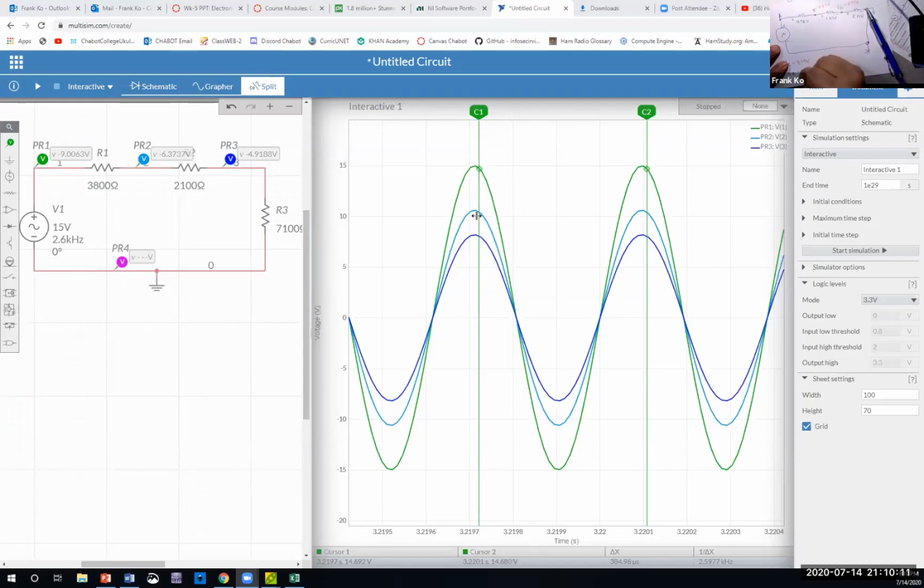10.62 volts, so that's 10.62 volts. And then the voltage at point A means my red probe goes way over here. Well, what is the sum of all three? Isn't that equal to my 15 volt peak? Okay, so that's where these voltages came from. Voltage at the first probe, voltage at the second probe, voltage at the third probe came specifically from